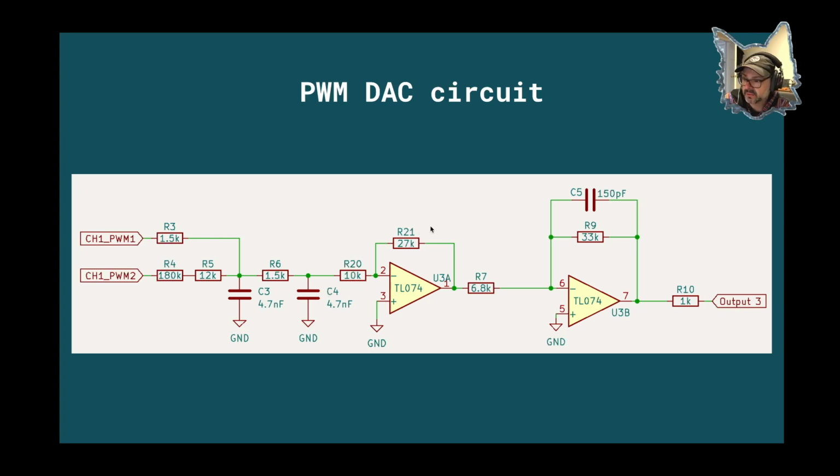So these values right here will increase the signal to about 4 or 5 volts peak to peak. I think it might be 4. I left this 33K resistor and this capacitor in here because this is an active filter, okay? And together with the 6.8. And this is here to also filter out some of that digital noise.